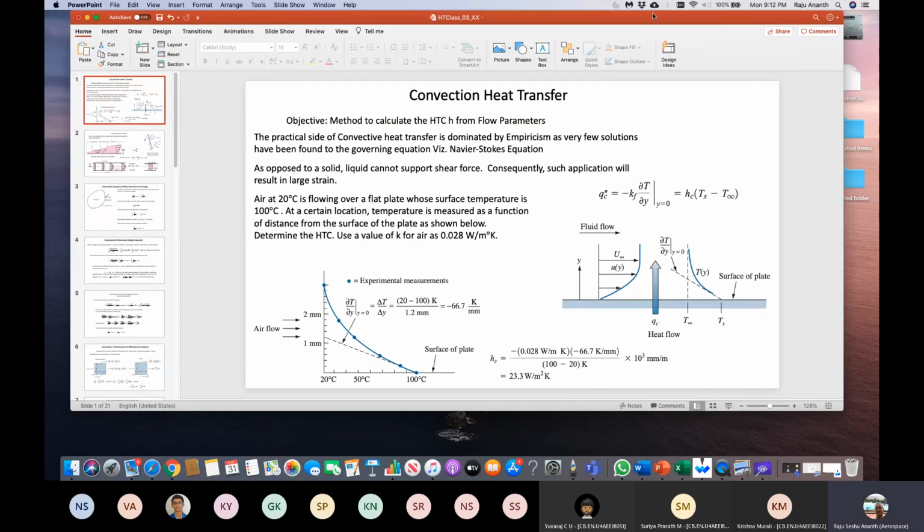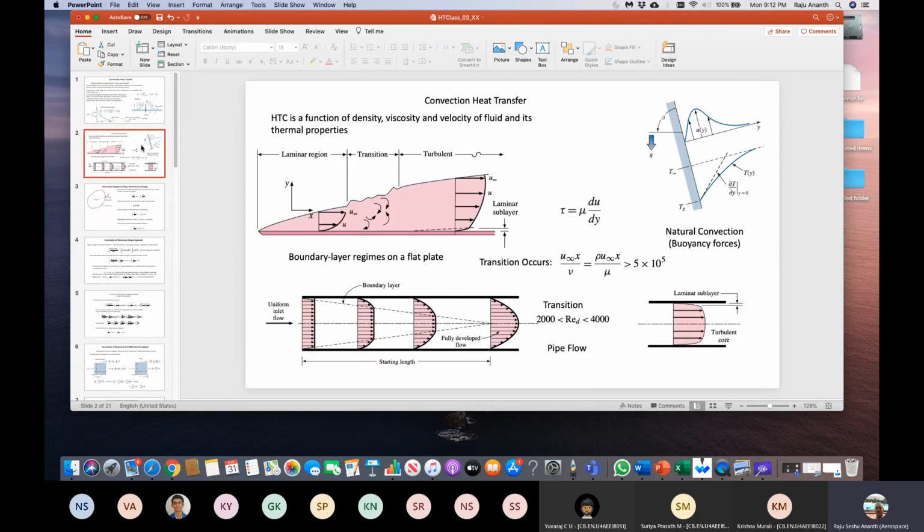Okay. All right. So again, I'm going to touch upon a few other areas. And I'm not going to dwell too much on turbulence, but let's assume a flow is going over a flat plate. We're going to consider very, very low velocity, so it'll be laminar. You might have already read it in your fluid mechanics, but just recollect that. So there is a laminar region. What happens is, I'm showing this in the pink color, the boundary layer is building up.